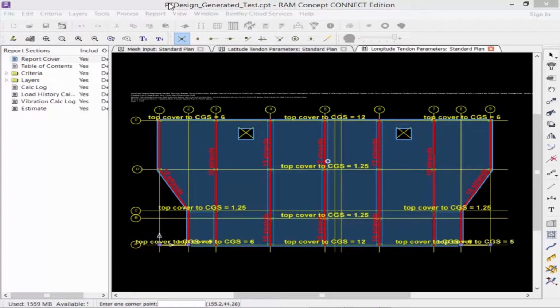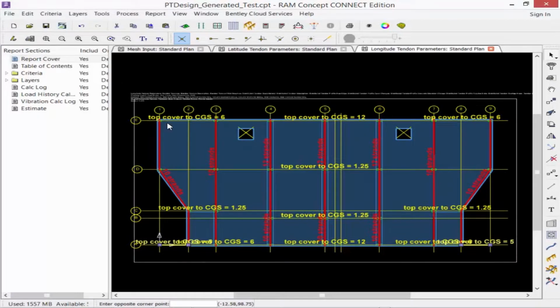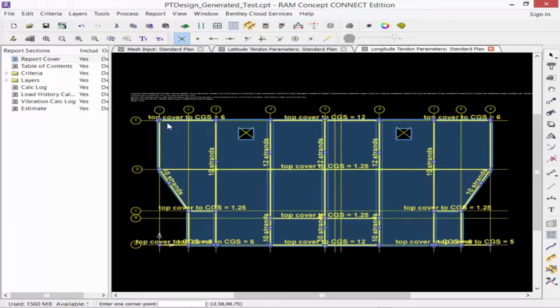Now that we have finished creating our support polylines, we could create our span polylines one of two methods. We could either, again, use this tool and select span instead of support, or we can use our support polylines to have the program automatically generate our span polylines, which is what we'll go ahead and do for this exercise. To do this, we must first tell the program which support polylines we want considered in this operation. So I'm going to use my selection cursor and draw a fence around the entire plan.